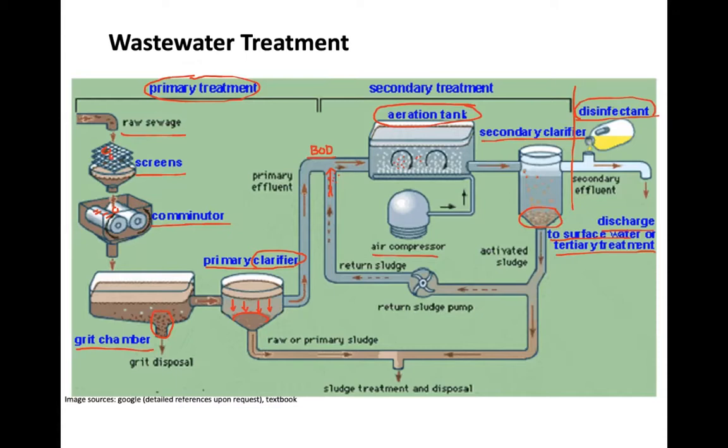So now we have dealt with the water, right? So we basically come up with relatively cleaner water from the raw sewage. This is clean water, raw sewage. Okay, so what happens to the solids? How are we going to deal with the solids that are coming out? So some of the solids are in the bar screens. So we can directly dispose of them in the landfill, right?